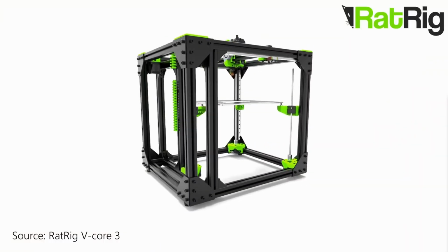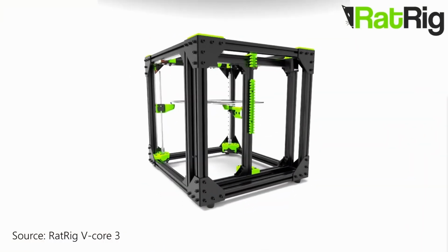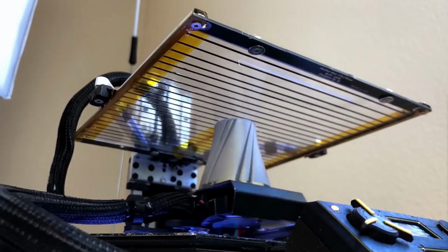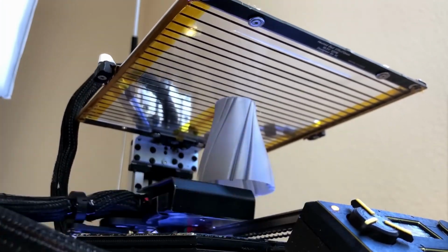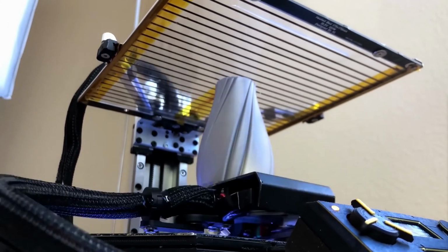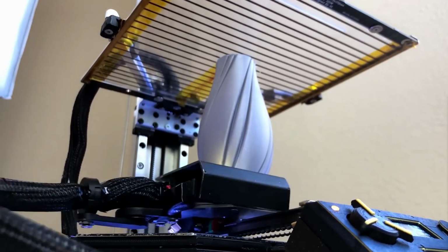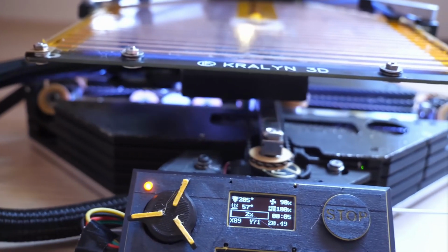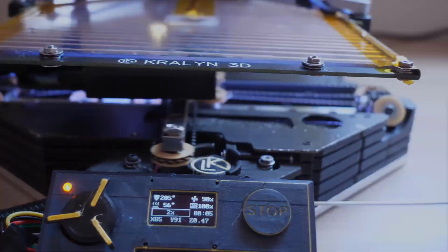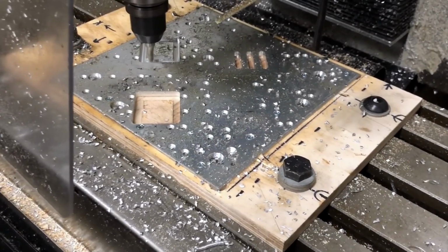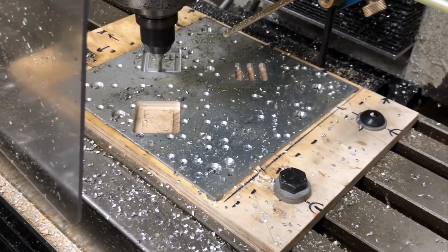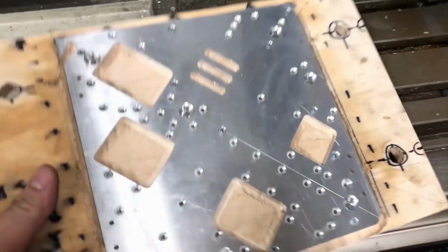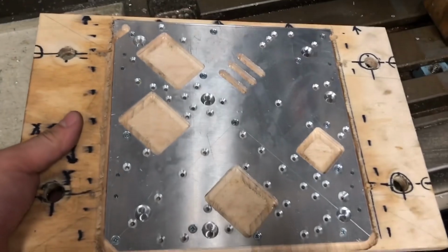So 3D printer designers add a heavy and thick frame to make the printer more rigid. But by flipping the entire printer upside down, the heavy moving mass is now close to the ground, no matter how tall the print is. This way, the center of gravity is always near the base of the printer. Thus, only a sturdy base is needed for the gantry to be stable. In this case, a 6mm aluminum plate.